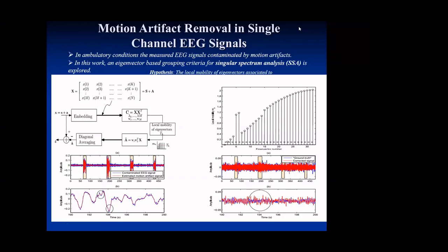But the problem is the accuracy. If I record a lot of signals, I can easily remove the noises and easily interpret the brain activity. But here, because you are measuring only a single signal, there may be chances of less accuracy. To overcome that, we have used different signal processing techniques, basically SSA, which I have explained earlier. I will record x1, x2, so on up to xn, total n samples of the single channel at different time instances, t, 2t, so on up to nt.